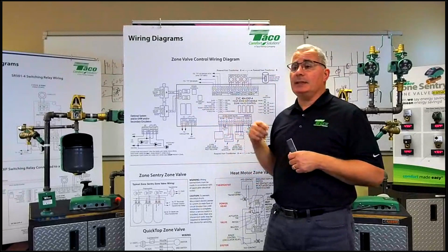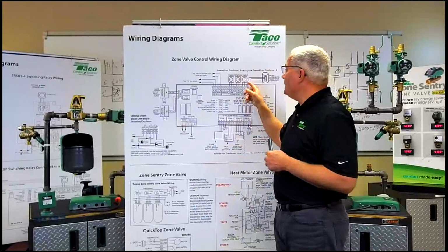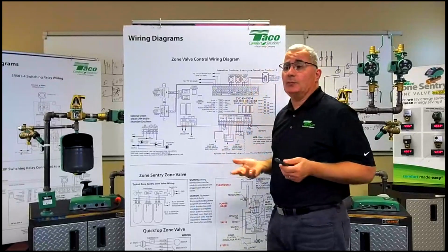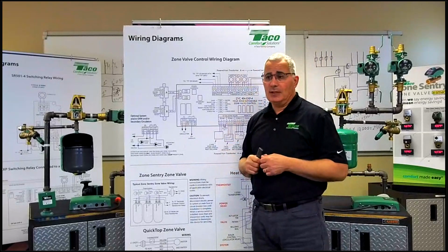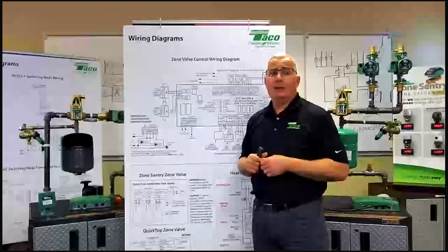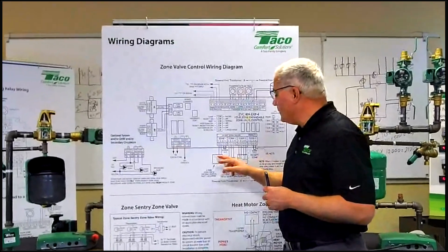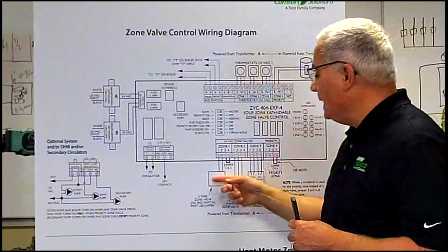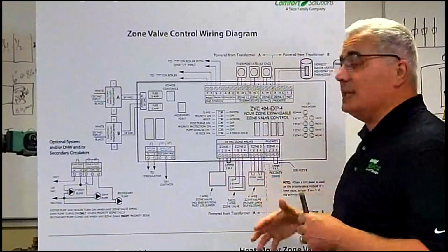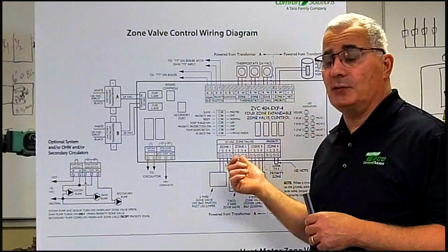Something to keep in mind, something that's coming up more and more often, you're using Nest thermostats. A lot of you guys will show up on the job and the homeowner says, here, this is what I want you to use. Or the utility gave it to me. I want you to use this on my job. And if you've got everybody else's zone valves down here, that combination of Nest and everybody else's zone valves is too much power. The Nest would actually need its own transformers.